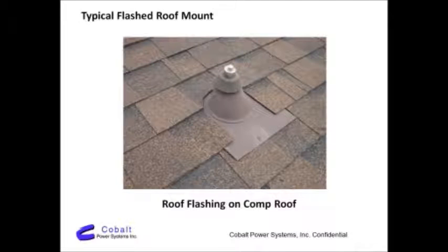So this is the typical mounting post that we use. This is a solid aluminum, 1 1/4 inch diameter post. It's bolted to the rafters. You can see it has a conventional flashing. So really, for you builders out there and architects and designers, you really treat it just like a vent pipe. It's just a penetration through the roof with a proper flashing and a rubber boot on the top.